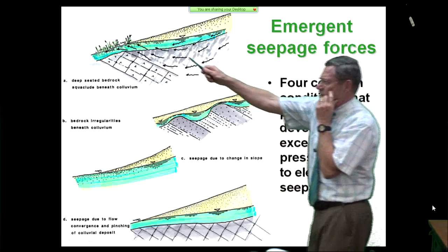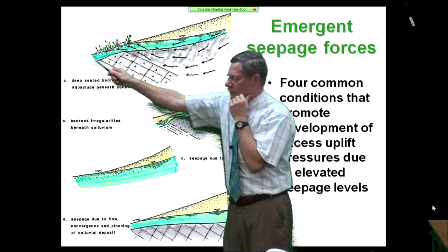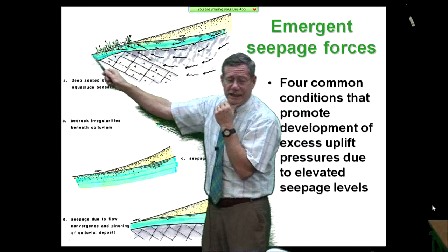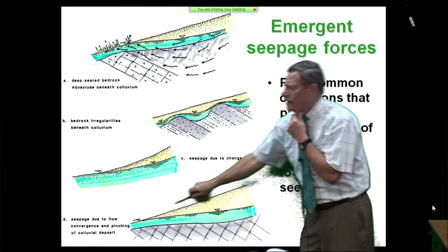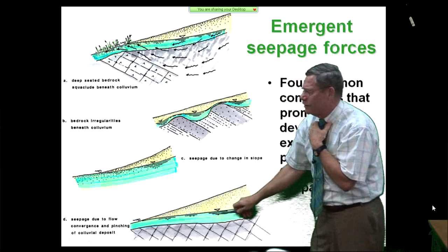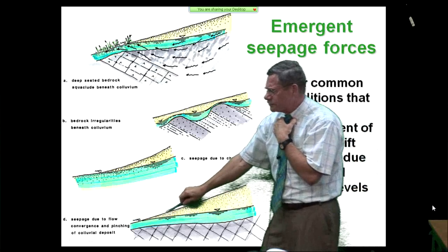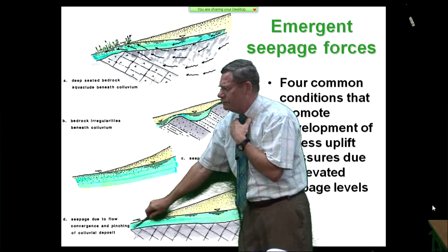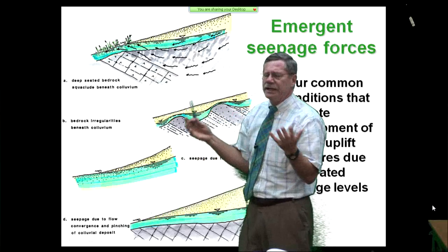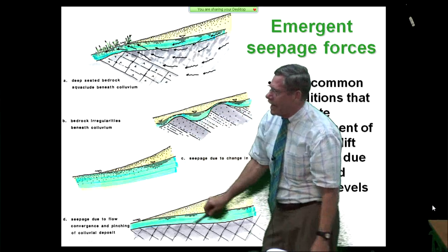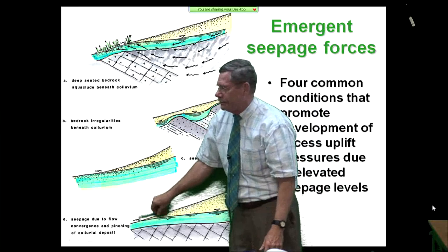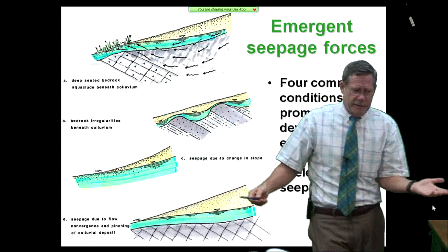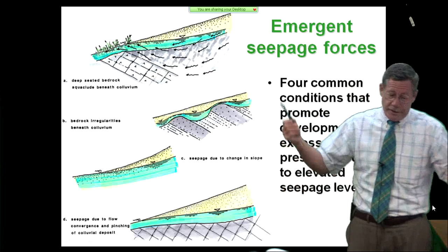This one was easiest because I'd see the foliage here. That was the dead giveaway, what was going on. This one, where I had the big highway embankment or a dam or something down here or a levee, this one's tougher because I only see this problem under limited conditions, where I have the high pore pressure down here. And then you'll see starting to pipe down here. So if you're not out there when the action's occurring, you'll miss that one.